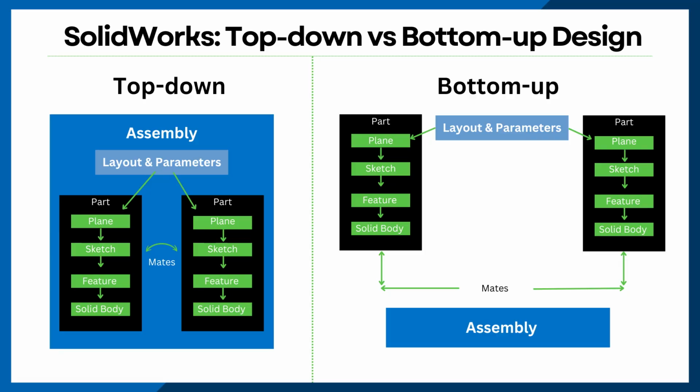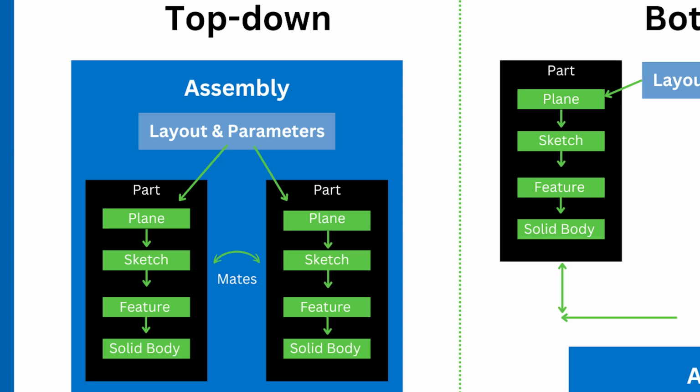Now there are many different ways to add clearances, just like there are many different ways to design parts in SolidWorks. You can opt to do top-down design or bottom-up design. A top-down design is when you focus on the assembly level structure first and then define the overall geometry, which then drives the creation of individual parts. This typically means designing a part within the assembly and using the master assembly constraints to relate your new part to.